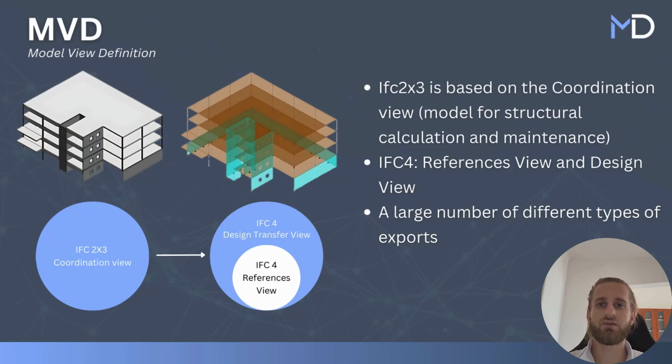There are many different types of reports. For example, you can see how the model looks when you export it for a structural calculation, where only the load-bearing elements are included. This is how the model appears inside the software for structural calculation based on what you sent. It is very important to understand MVD because it is crucial when coordinating with several different models. It shouldn't happen that people send the same models, causing overlap and double quantities. You must know exactly what the architect sends, what the construction engineer sends, what the structural engineer sends, and so on.